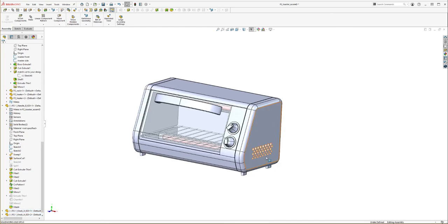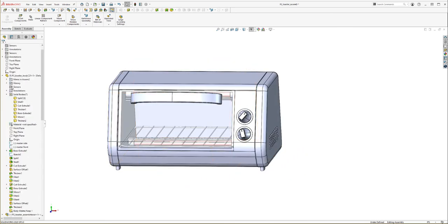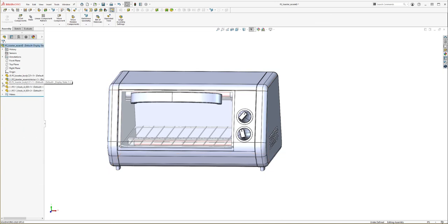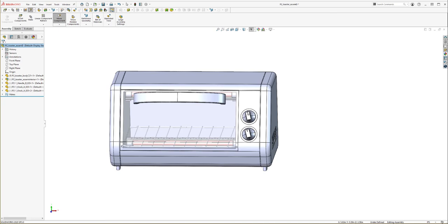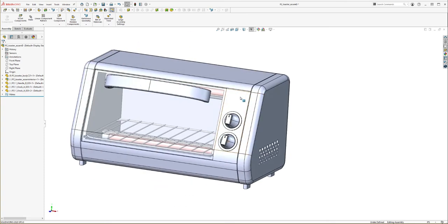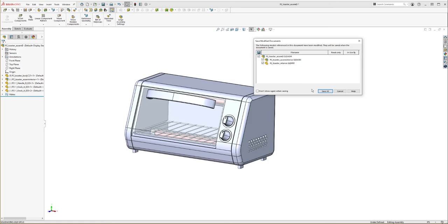The final thing you need to do, because this is like an InDesign file that's pointing to all of these different elements, is you need to package it properly, especially in order to submit this file for review. This also mimics working with other people when you need to share a file with someone else, especially if it's an assembly. This is a critical component. So you can simply hit save.